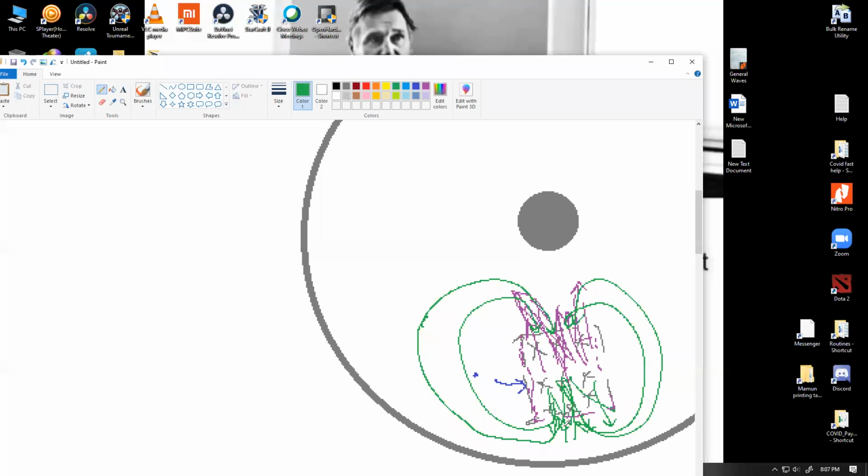So other electrons will essentially rush into this place. This would produce a cyclic flow of electrons. Electrons will be coming out through this direction, and they're going to fill it up on this direction. If this is the direction of the electrons, I can draw the conventional current, which is essentially called the eddy current, in the opposite direction. So eddy current will be happening like this, and conventional current and electron flow will happen like this. There'll be a pretty high amount of current produced by a lot of electrons within the metal piece because of the application of a magnetic field onto this disk.